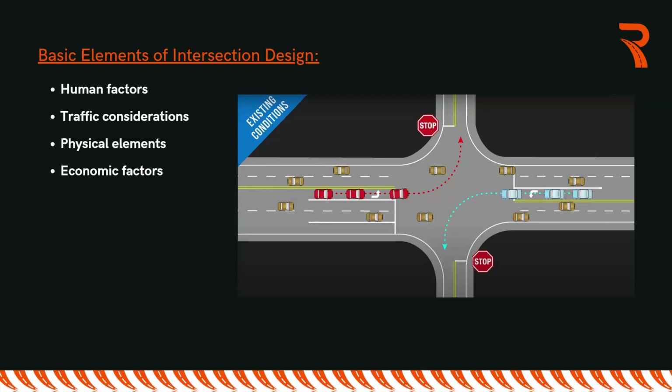Gentlemen, please. So we are talking about the conflicting area. That is where you see displaced lane. That is where you see engineers adding, for example, some slip roads that can evacuate traffic at that specific point. That is where also we provide speed change lanes and also storage lanes at that specific point in place. And then, of course, we'll be talking about whether this intersection requires to be traffic controlled. Is it signalized? Or what type of intersection is that? And then we'll be talking about also lighting, roadside design, environmental, crosswalk, driveways, and also access management.